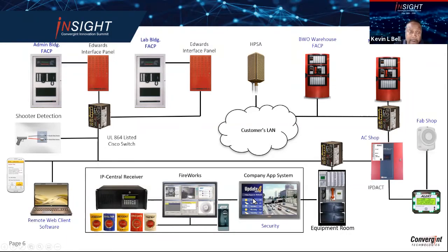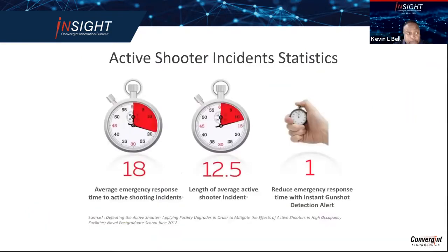We can incorporate fire alarm. And if you have a small building that doesn't have fire alarm, it doesn't have a paging system for us to integrate into, we can put these beacons in there with these self-amplified speakers, and we can put mass notification in any small building, shop, or medium-sized building with just this beacon that only requires Cat5 with PoE and a self-amplified speaker. And this is very cost-effective.